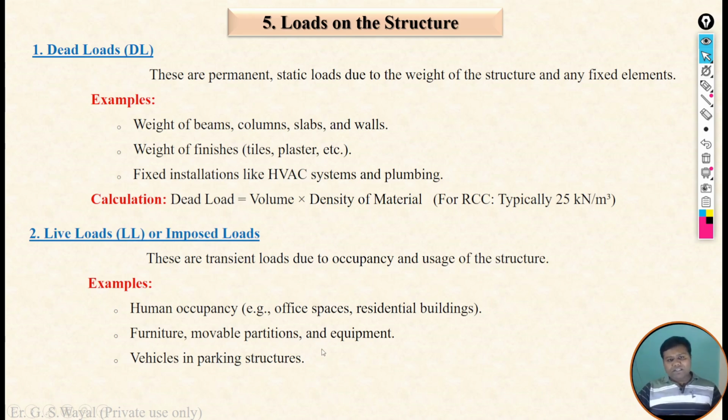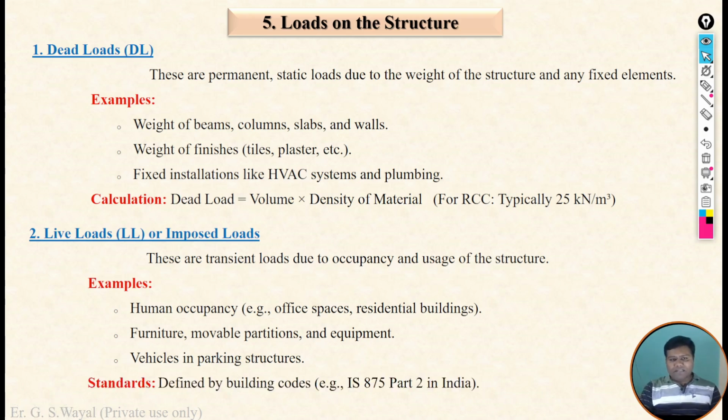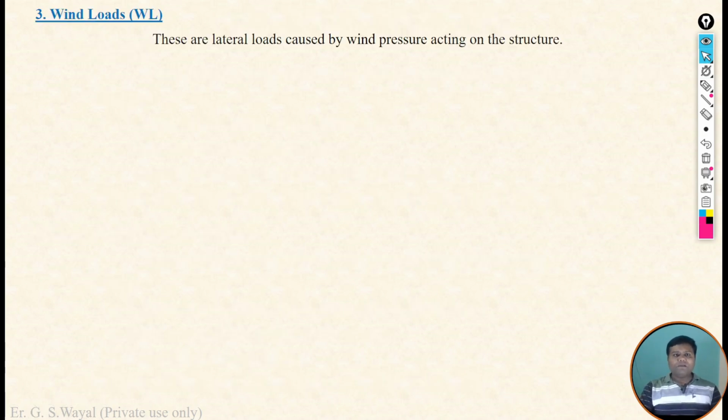Furniture, movable partitions and equipment also come under the live load. Vehicles in parking structures also come under the live load. The standard we generally use to consider the live load on the structure is IS 875 part 2. Next, wind loads.